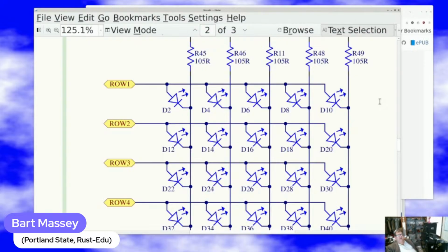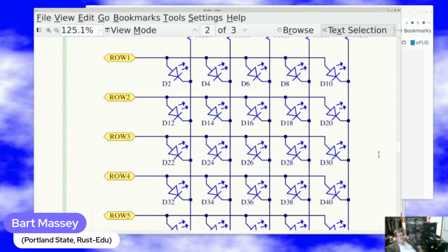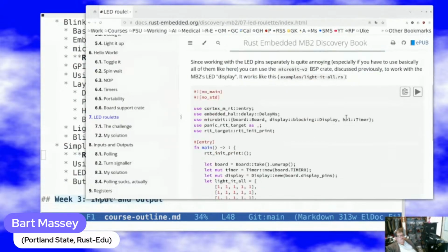And so what we do is we actually light up a row at a time. We light up whichever LEDs we want in that row, and then we turn it off and light up whichever LEDs we want in the next row. This is called scanning out the rows. We turn on what we want in the first row, then turn it off and turn on what we want in the second row, and then the third row, and then the fourth row, and then the fifth row. And if we do that fast enough, it'll be just like that thing we saw earlier. It'll be happening so fast that we can't see it switch, and all the LEDs will take turns being on, and it will look like everything's cool. So if we go back to our original thing here up at the top, the slowed down version that I was going to show you.